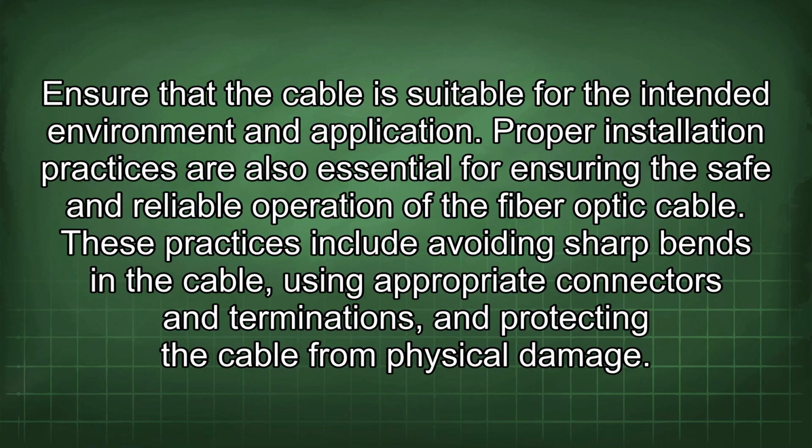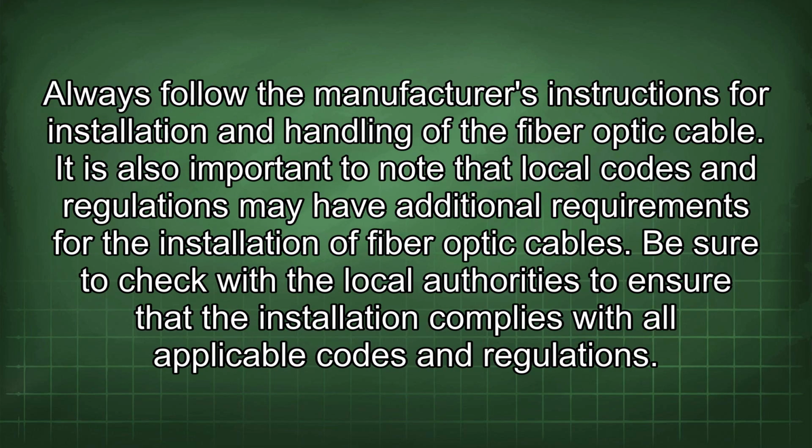Proper installation practices are also essential for ensuring the safe and reliable operation of the fiber optic cable. These practices include avoiding sharp bends in the cable, using appropriate connectors and terminations, and protecting the cable from physical damage. Always follow the manufacturer's instructions for installation and handling of the fiber optic cable.